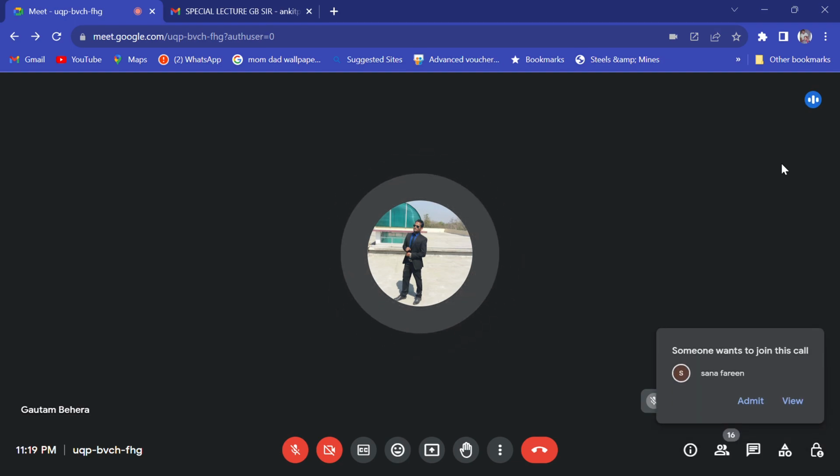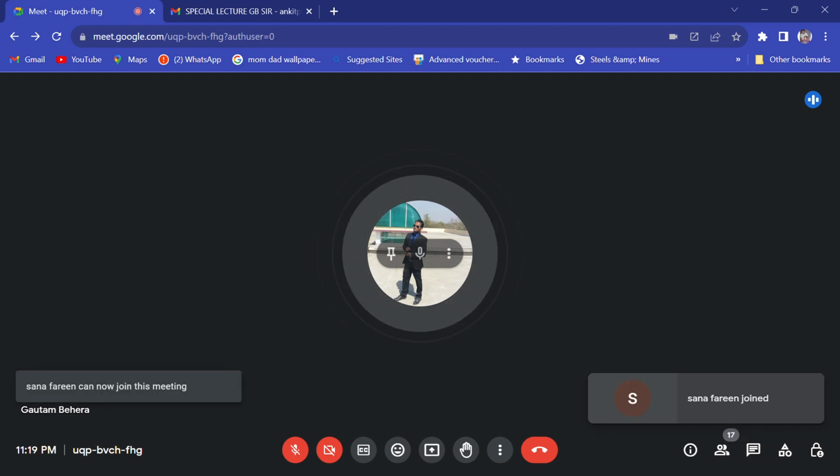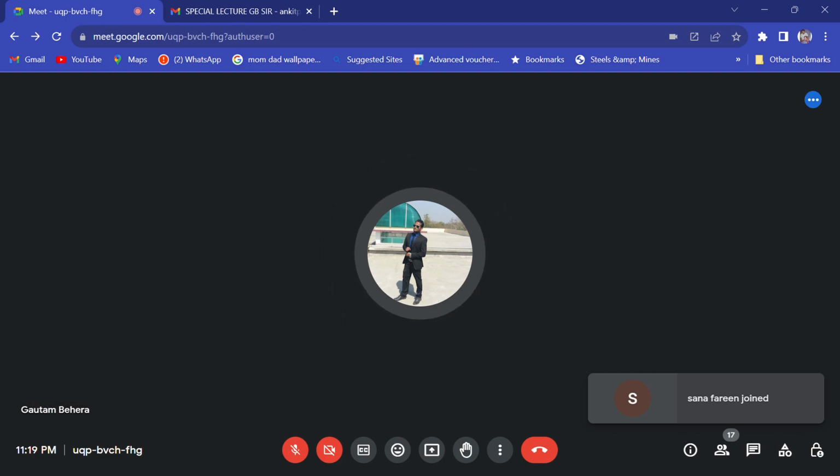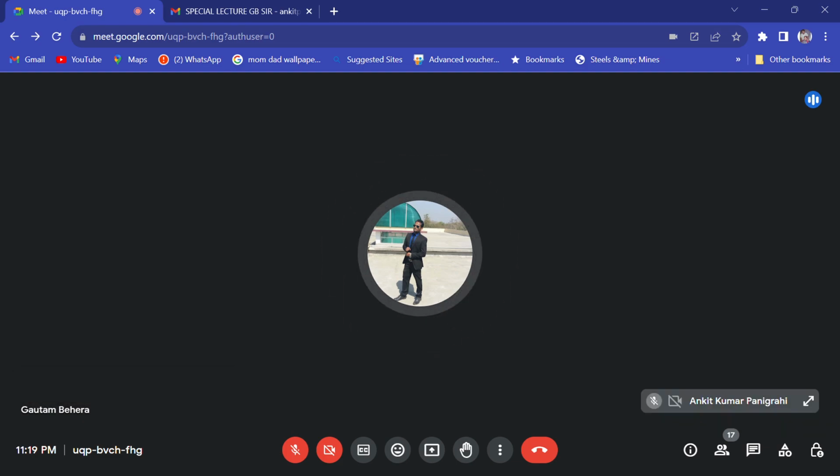Phosphorus and silicon form acidic oxides. So if you want to remove them into the slag, you need high basicity, like basic oxides. That's why you add more lime into the process to make the slag more basic, so that they remain in the slag. Their activity is reduced because they form strong bonds with basic oxides. Is it okay, or shall I repeat? Is it okay why we maintain high basicity in the steel making slag?